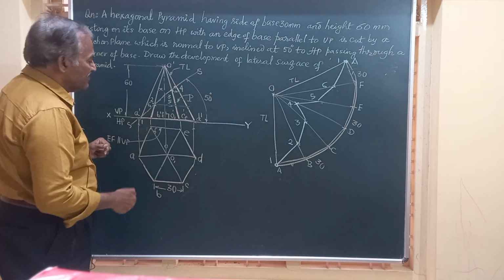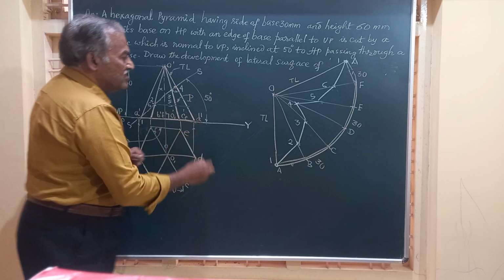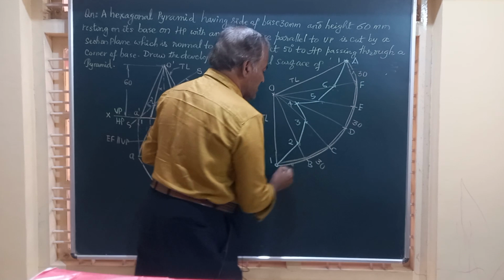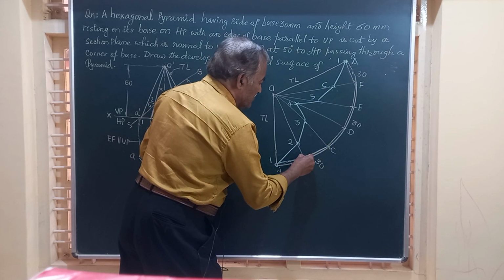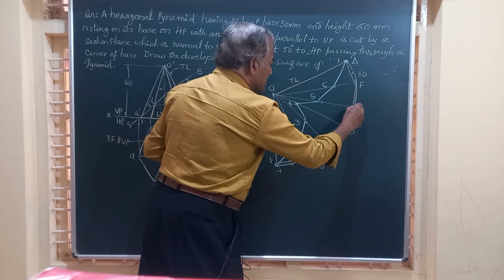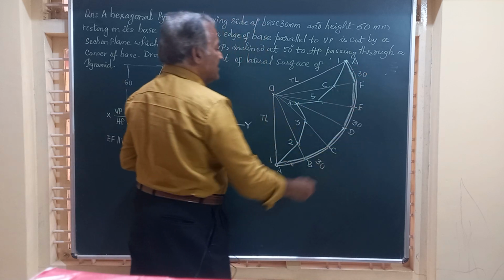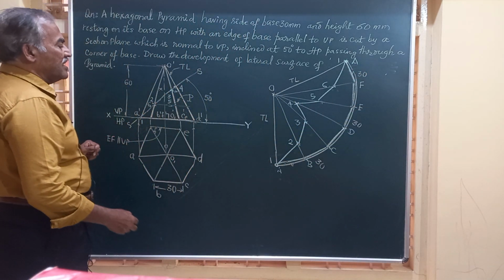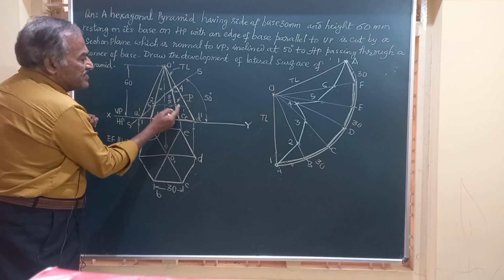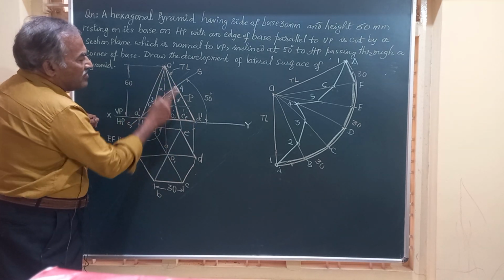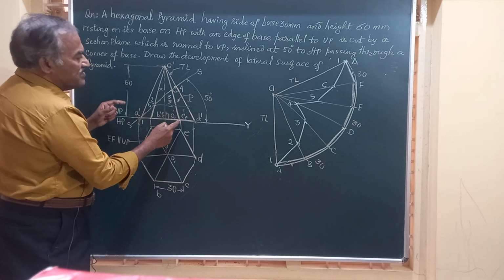And if you observe the figure, friends, the complete base of the solid is intact. So I have to show all these base edges, namely AB, BC, CD, DE, EF and AF by dark lines. And friends, the portion between the section plane and the base is intact. That is, on OD you should have this length, and on OC and OE you should have this length.